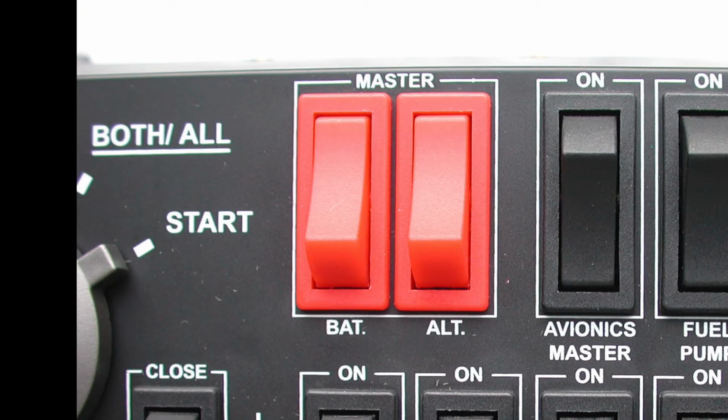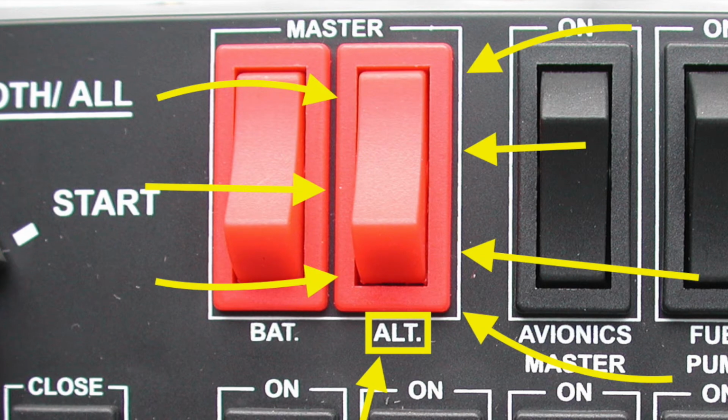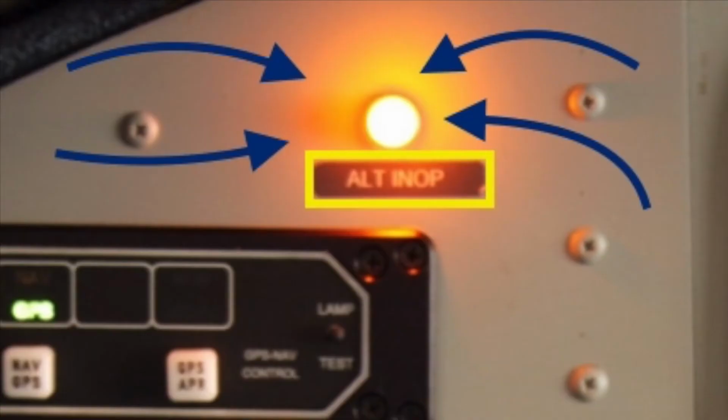The electrical system is powered on or off with a master switch. When the master switch is turned on, it provides power to all circuits except for the ignition system. The battery switch activates the electrical system so that the battery powers it. The alternator switch controls whether or not the pilot wants the alternator to be a part of the circuit. A pilot may turn this off in the event of an alternator failure. In this case, the entire electrical load is placed on the battery. It is advised that all non-essential electrical equipment should be turned off to conserve battery power.